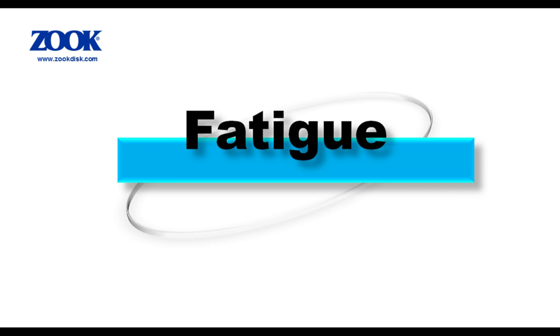Another cause of fatigue can simply be operating ratio. It's important to understand marked burst pressure versus specified and manufacturing design range to ultimately know what pressure level of disk you will receive. We've had many cases whereby a client suddenly experiences performance problems, and the cause is simply that the latest lot of product has been marked at the low end of an agreed upon design range. Remember the minus 10% MDR example from earlier on. In this case, the specifications need to be reviewed in order to ensure the disk manufacturer is producing a product that will ultimately work in the field. This could result in a disk model change, but it can often simply result in a slight specification adjustment.